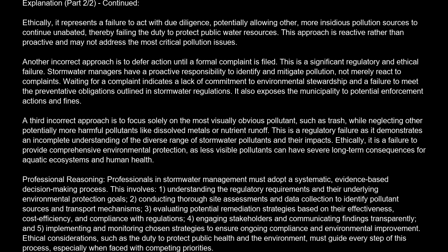A third incorrect approach is to focus solely on the most visually obvious pollutant, such as trash, while neglecting other potentially more harmful pollutants like dissolved metals or nutrient runoff. This is a regulatory failure as it demonstrates an incomplete understanding of the diverse range of stormwater pollutants and their impacts. Ethically, it is a failure to provide comprehensive environmental protection, as less visible pollutants can have severe long-term consequences for aquatic ecosystems and human health.